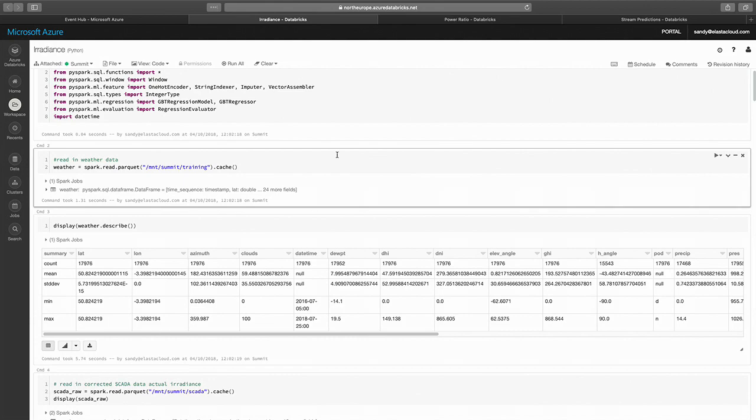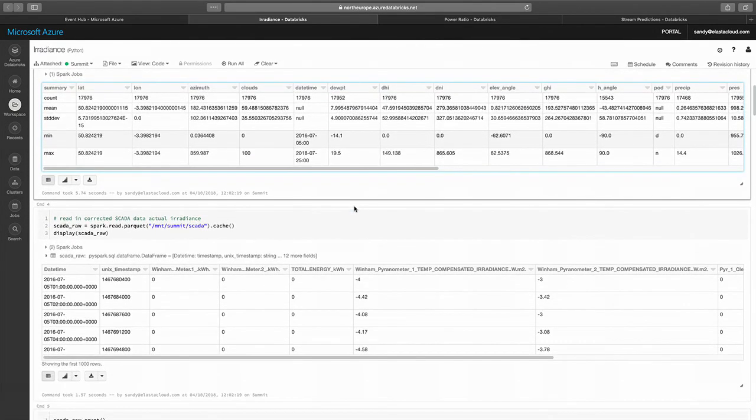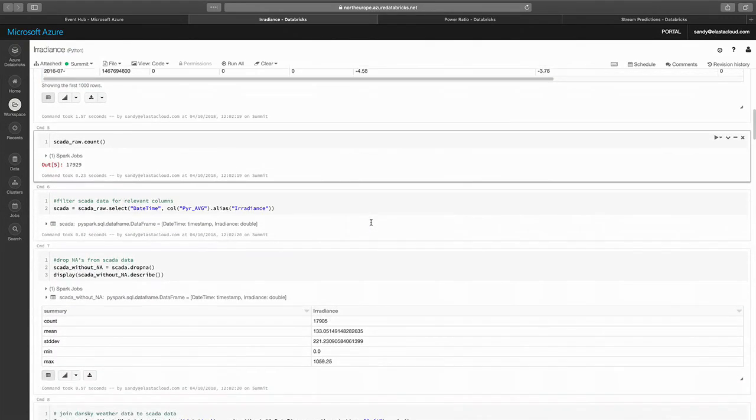You can calculate the value of irradiance that you would receive at a certain point on the ground at a certain angle. So most of our panels are angled at between 20 and 24 degrees in the UK, I think. So we can generate a prediction straight off the bat if conditions were absolutely perfect. No cloud cover, no rain, nothing like that. We know exactly what that value would be, and that's one of the most important features to our model, as well as UV indexing. So what we're using for the model predominantly is UV, clear sky, as well as the seasonality.